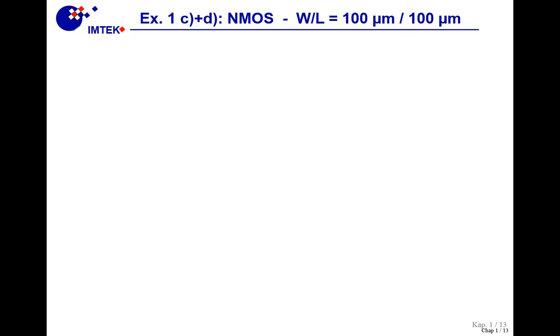Now the last part is telling you that it is intended to use a transistor as a 3 microampere current source. You are supposed to calculate the needed gate source voltage first when you have lambda equal to 0, and then with the lambda that we just calculated right now.